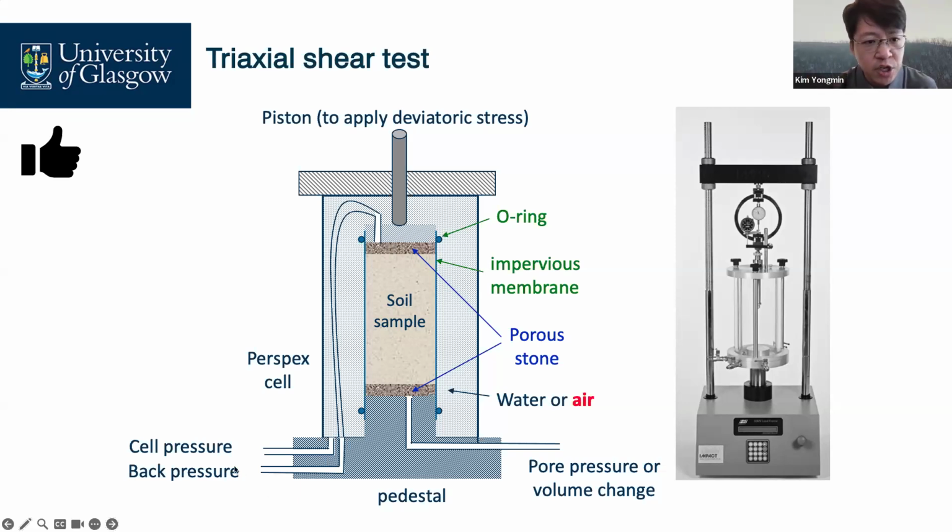And we have another channel, the cell pressure. This is not linked to the soil, but this cell pressure is connected to the inside of the cell. It means that this cell pressure is sometimes water pressure or air pressure. In our school, it is air pressure. This air pressure applies confining pressure to the soil sample to simulate the soil's in situ stress.